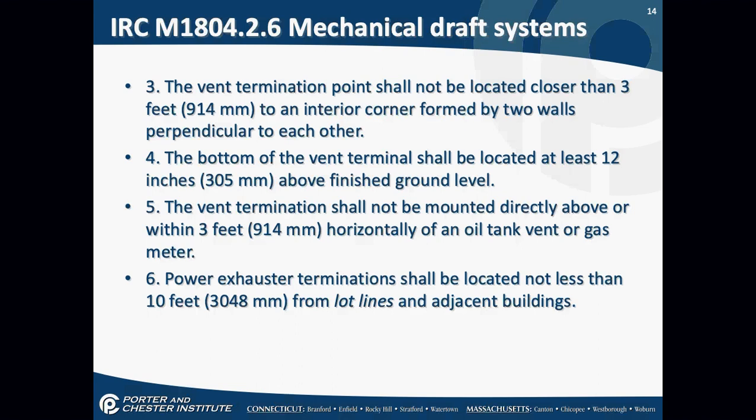Why does number 5 exist? The vent termination shall not be mounted over or within 3 feet of any oil tank vent or gas meter. What's my reasoning there? Vents produce heat, don't they? Yeah, this is classified under things that go boom. Because there could be vapors here. Vapors are extremely explosive. Gas meters have what's called a pressure regulator that sometimes vents just to the outside.